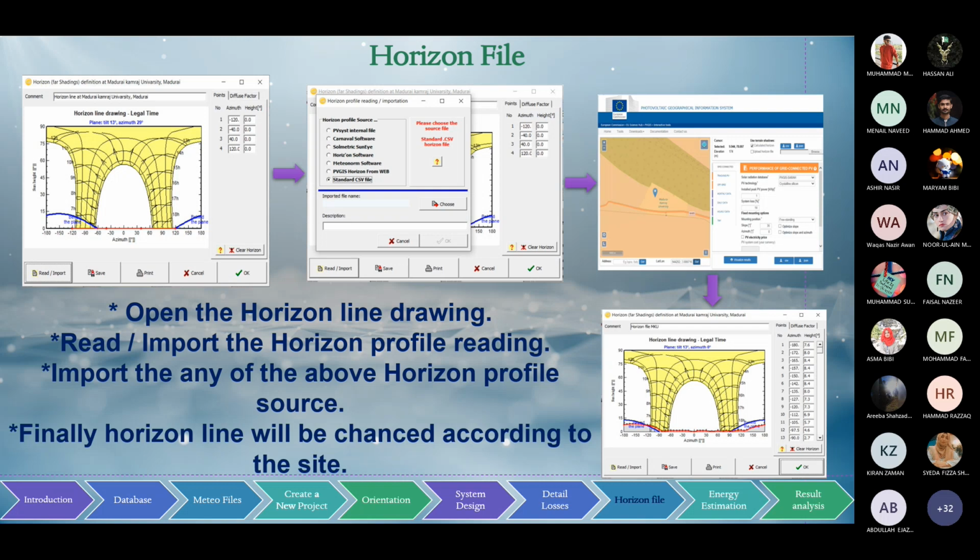Similarly, another software is Google SketchUp, along with a skeleton model. So we can draw the entire solar PV model along with the obstacles. Once the SketchUp model is done, we can directly import the 3D file into the PVsyst software. Just run it, and we can get to know how much shadow losses will happen. The shadow screen, everything, we can estimate in the horizon file.